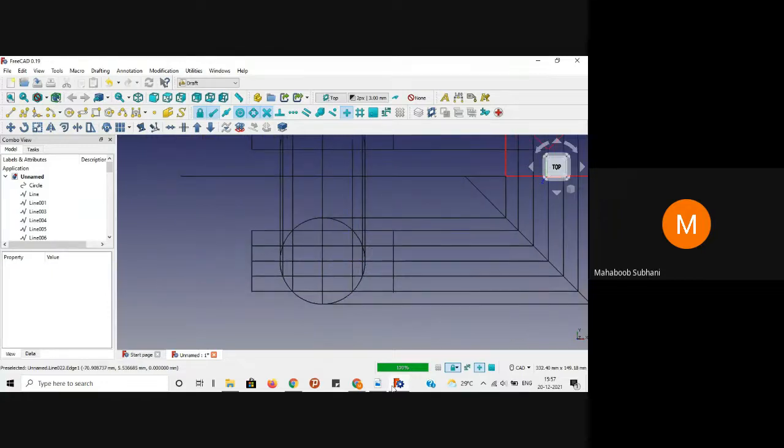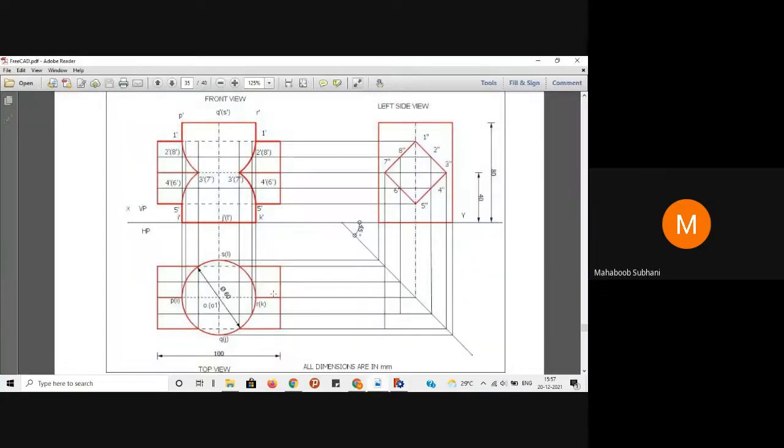Now we will highlight the top view. If I look at the same intersection of solids from the top view, the outer part of the diameter, that is the cylinder, will be visible, and whatever is left out of the prism, only the outer part alone will be visible. Why? Because it is a solid cylinder, what happened? It will be invisible.